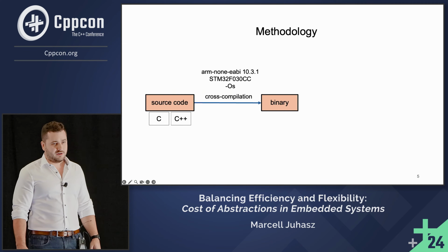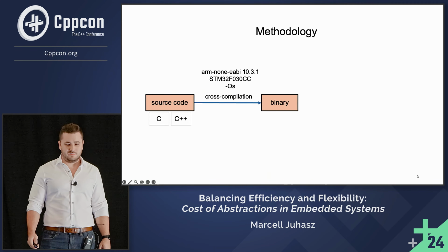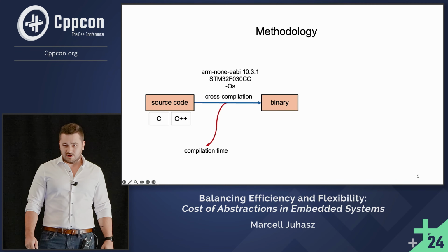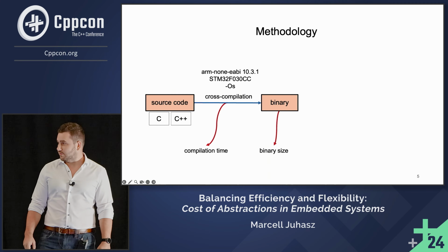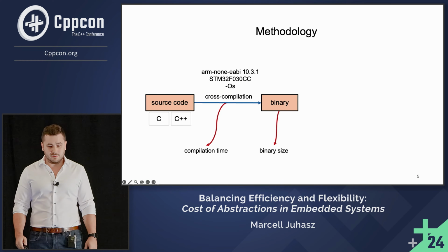I cross-compiled the projects for an STM32 microcontroller. I optimized for size, as it is often a limited resource. In this step, I could also measure the compilation time as well, and assessing the size of the binary of a compiled project is pretty straightforward.